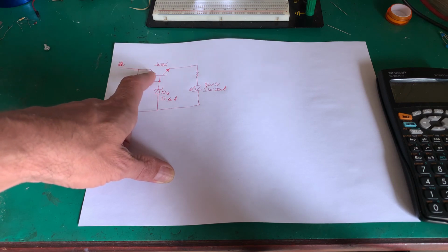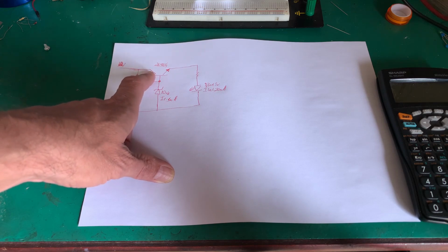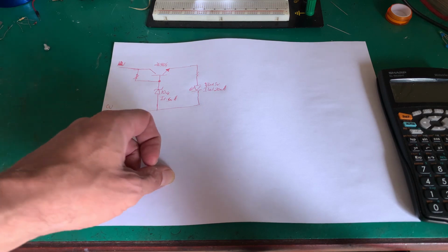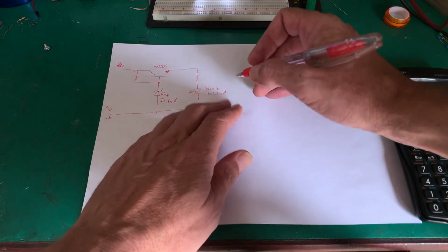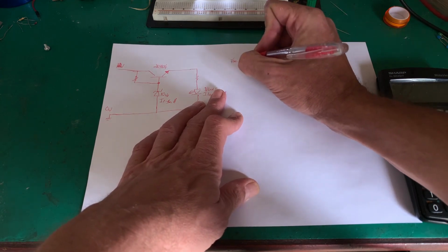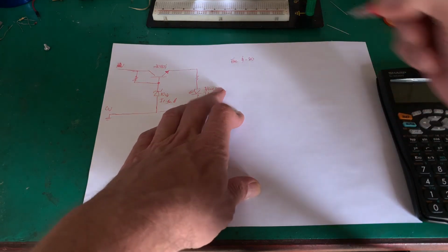The gain at a collector current of 50 milliamp is 60. We want 20 milliamps, so we can take a gain of roughly 80. So I'm going to say my HFE or beta is 80.